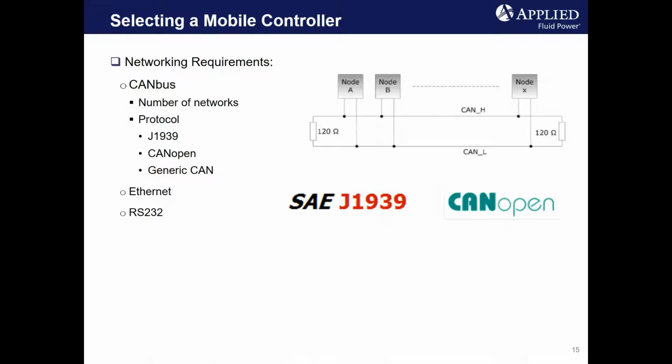For applications that call for more advanced sensors, such as vision sensors, there is a need for serial communications that can handle more data. This is where Ethernet and RS-232 come into play. Typically, Ethernet and RS-232 exist in industrial applications. They're also becoming more popular in the mobile world, with telematics becoming more and more relevant. Telematics allows for remote connectivity, remoting into and going online with a controller, or remotely flashing programs and program files faster.